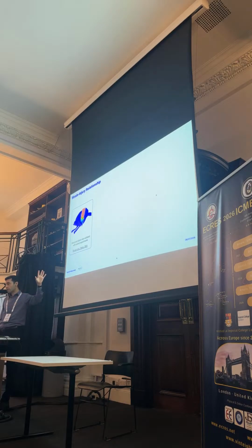One study we did was on rodents. Why? Because this was a much more controlled loading condition than in humans. In humans, often we don't even know what the loading condition was. So you see a finite element model of a rodent head. We open the skin, drill a hole in the skull, and then hit the dura, the sac around the brain, with that impactor. That happens in 0.4 milliseconds, a really, really short time. And then we can predict the distribution of this maximum principal strain around the impactor and across the brain.